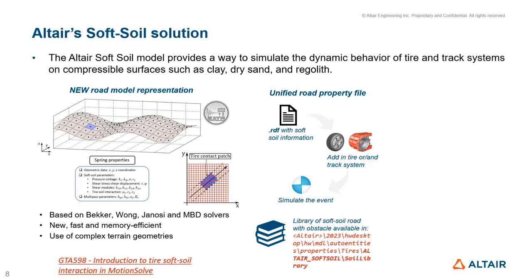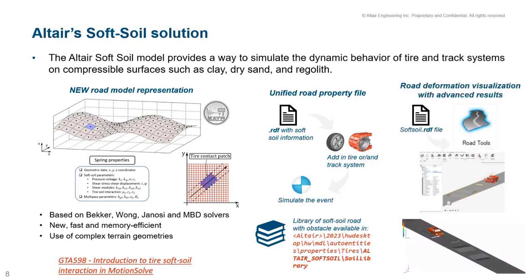For those who do not have this information about the soil, we are also providing an installation package that contains several types of soil data that can be used. And if you want to visualize and study the effect of the vehicle on the terrain regarding plastic sinkage, shear, and stress strain, we can also load these soft soil files into MotionView road tools and visualize the deformation of the soil.